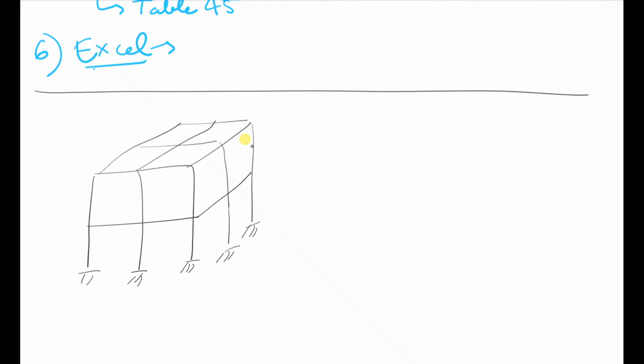So when we are given some loading, depending on the type of the building, say this is a library, then there is a load of books. If that is public property, then there is a general live load that we take with an increased factor. If there is a residential building, we take some standard loads. So some loads are there on the slab. These are the slabs. On this floor, this is the slab.